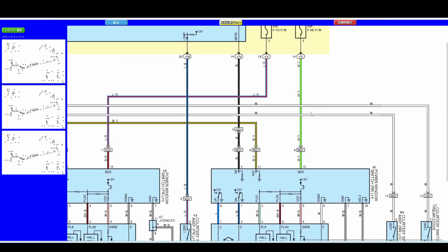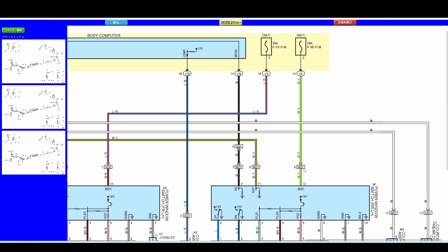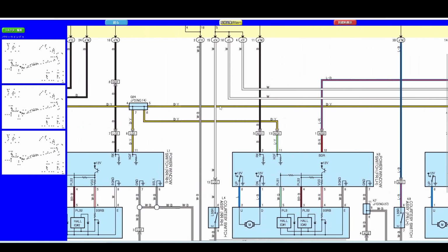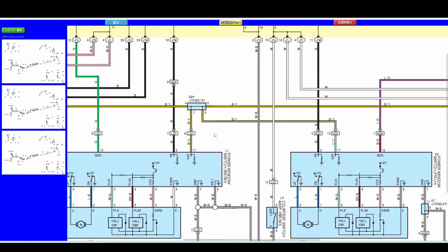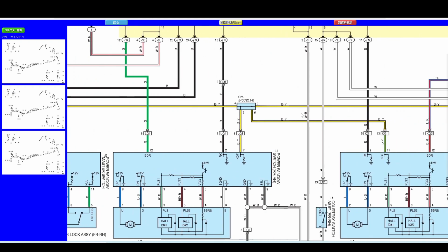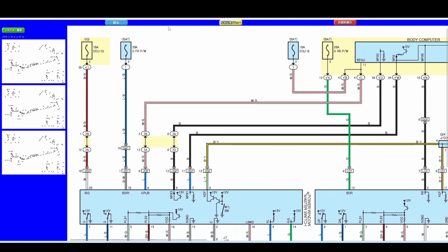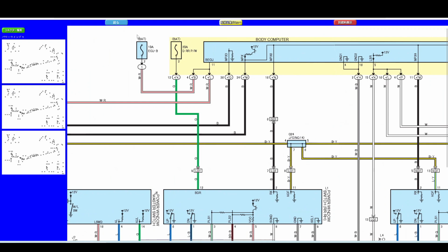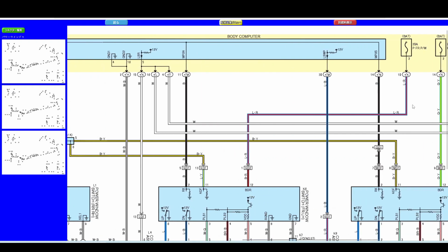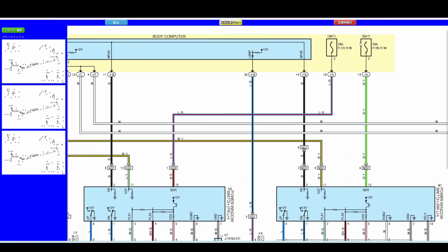Then we have our master switch. We have 2 grounds, and then we've got permanent battery power on this line here. And then there's this line that comes across, and it bridges to all the switches. And what is that line? Well, let's see what it is. If you notice, up here, we've got permanent battery power to this switch. Permanent battery power is also on this switch here. Then this switch has got its permanent battery power here, BDR. And this switch has got the BDR permanent battery power.